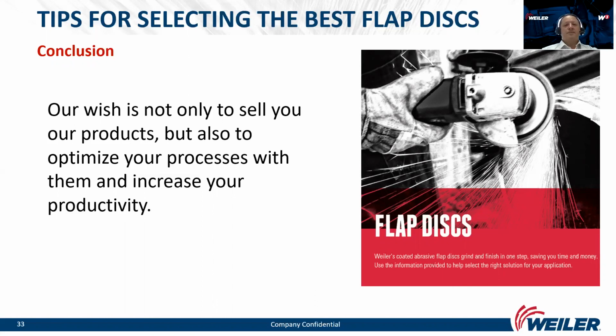The second question: for ceramic flap discs, what are the requirements for angle grinders? Yes, with ceramic flap discs, we must be sure that we have enough power, so that during the grinding process the revolutions do not fall down. If we hear the revolutions falling down, then something is not right. That's why we need angle grinders with power of 1,400 watts and more.